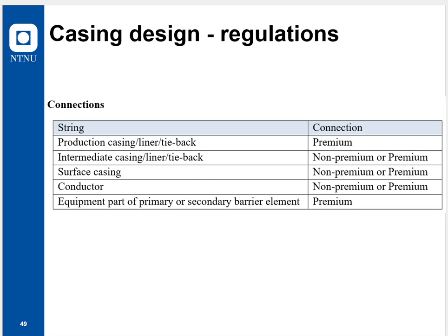So, where things become a little bit more complicated is where you actually cannot read the pressure in the annulus. What has been, I wouldn't say a problem or a headache, but a theoretical challenge would be the B annulus in subsea wells. There used to be no system for reading off the pressure in the B annulus, and what you had to do in your casing design was to basically design for what we call annular pressure buildup.